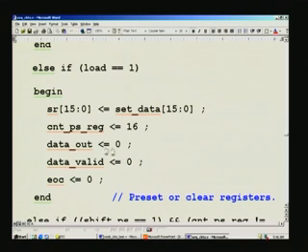That is what we want. And we also have a counter inside. Here that counter is preset to 16. This keeps track of the number of bits that have been sent out. Say you want to send 16 bits of information, that is the reason why it is 16 here. And data out and these things are not to be active as yet, so we just retain them as 0.